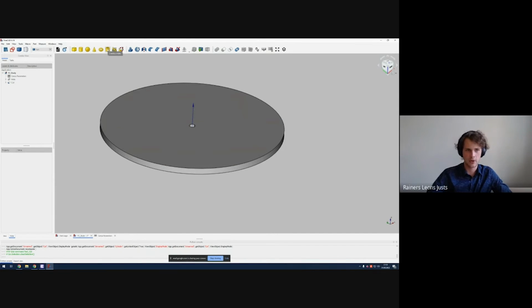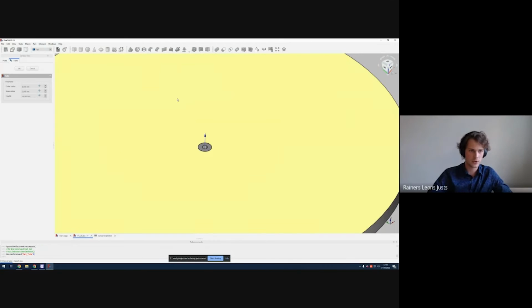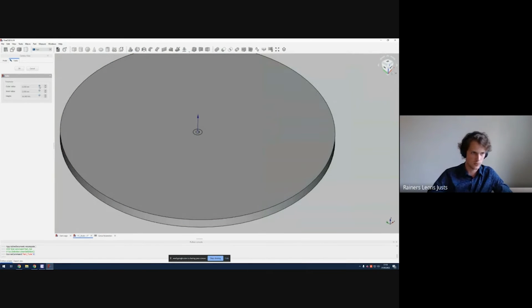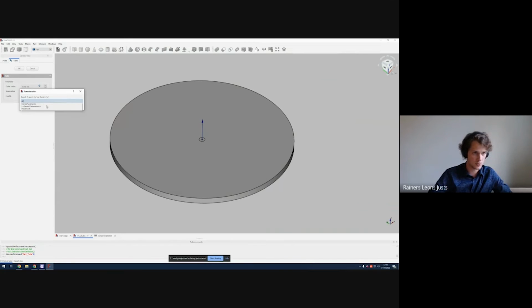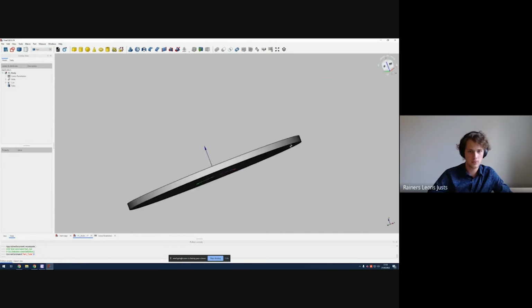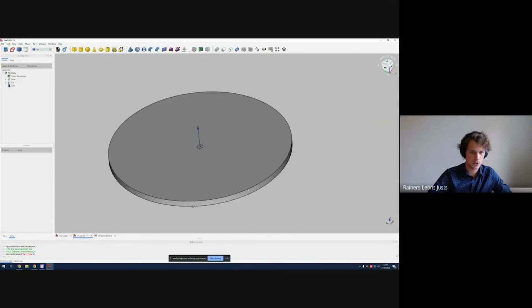We'll use the create tube, and we'll assign the parameters immediately as well. We want the outer radius to be CENOS parameters, outer radius. And I want the inner radius to be the same as the wire thickness. So CENOS parameters, wire diameter, divide that by 2 since we need the radius, and press OK. The height should also be the same as the ground. So ground thickness. And now we have our disk and the dielectric.